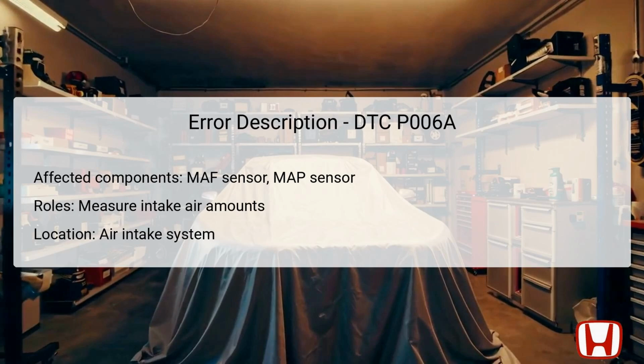In contrast, the MAP sensor evaluates the pressure within the intake manifold, allowing the PCM to calculate the engine's air-fuel mixture optimally. The MAF sensor is usually located in the air intake duct, just before the throttle body, making it critical for air measurement to prevent lean or rich fuel mixtures that can impact engine performance.